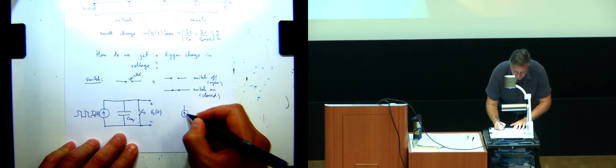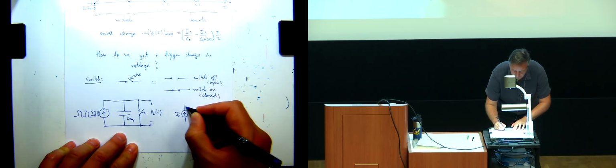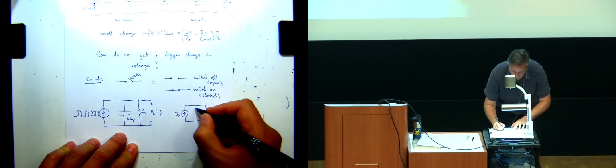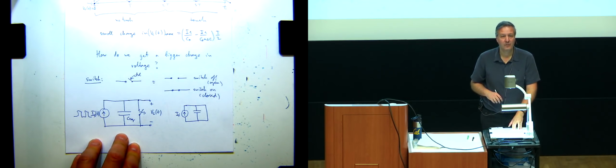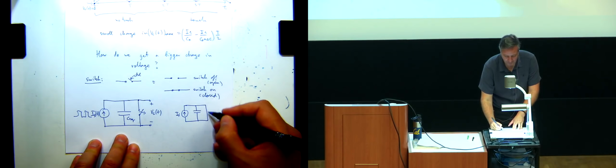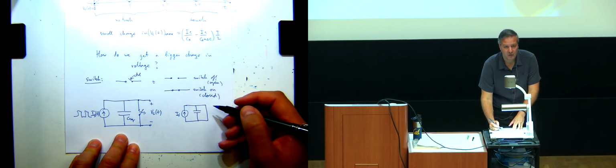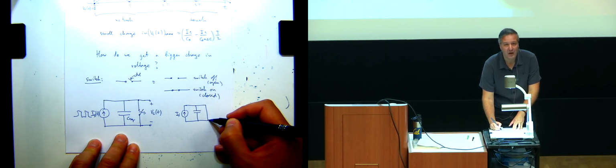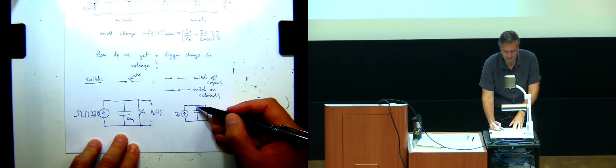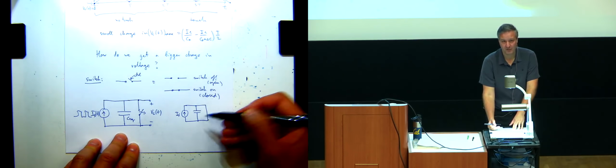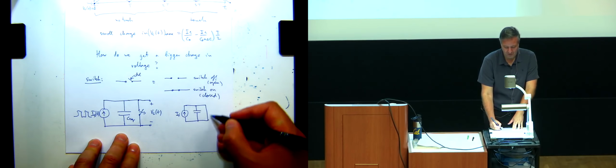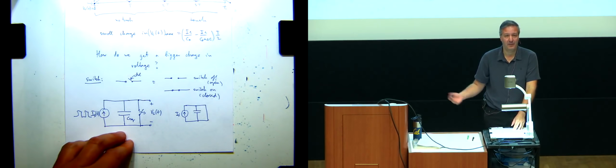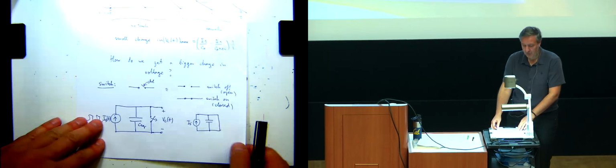So you're worried about this situation, IS? It's a current source. It's going to be good, right? Because in this case, this is just a wire, so the voltage across a wire is 0. We know that if there's a constant voltage across a capacitor, which in this case is 0, the current through the capacitor is 0. So all the current is really flowing through the wire, nothing happens. It's cool. Okay, yeah, good question.